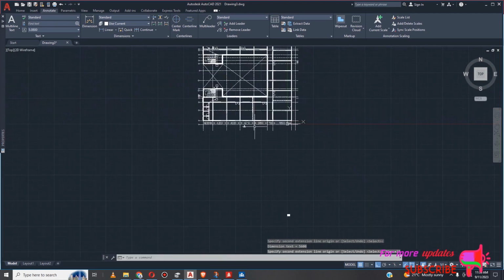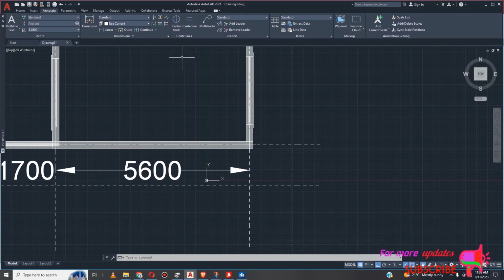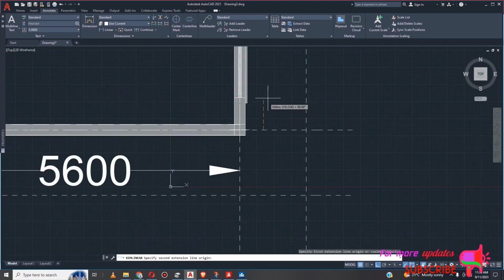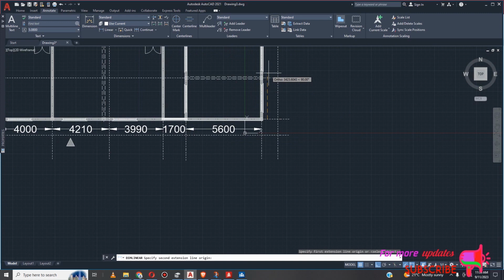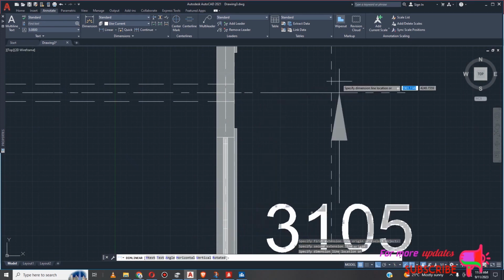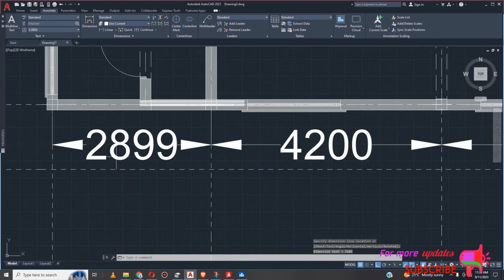Now measure the distance from there to here, then snap. You can hold Control because it can move away, then measure other lengths. Possibly that was the reason we found 8,929, because I believe this one should be 900. Let me check.